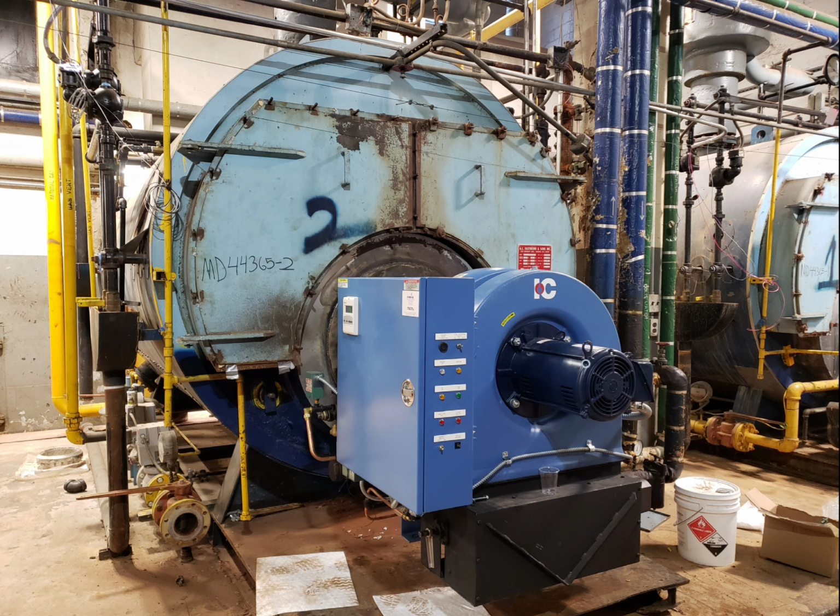And if anybody knows anything about steam heating systems, what happens when a steam heating system stops? When everything dies down and the pressure is completely depleted, it doesn't just remain as it is, it then starts to generate a vacuum. Why does a vacuum get generated? Because the steam that's inside the system is now collecting and condensing back into water. And since there is nothing in there to fill that void, it creates a vacuum until air vents start to open back up again and pull air back inside of the system. So this is another reason why with big boilers, big commercial boilers, you never find them running at 2 psi.